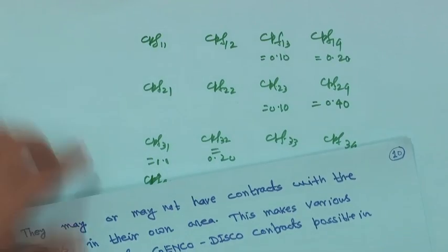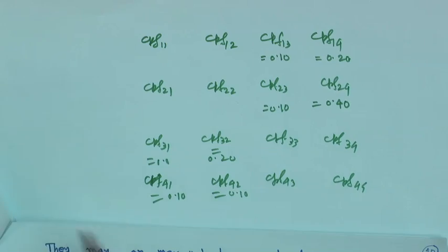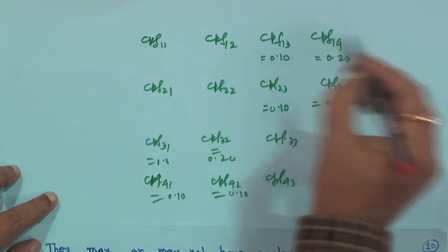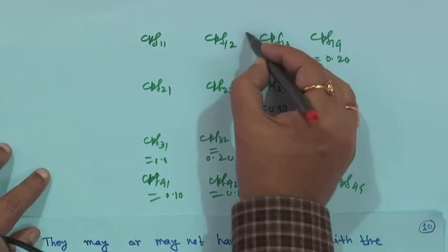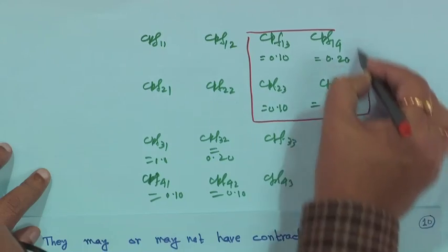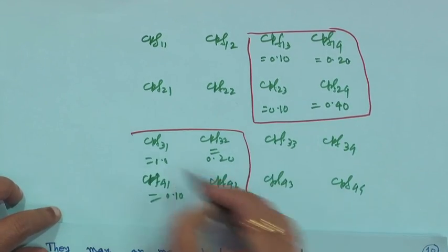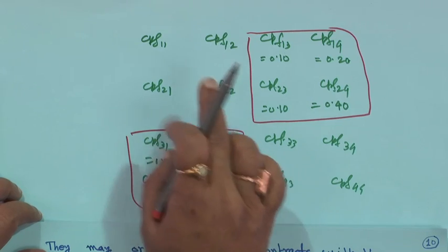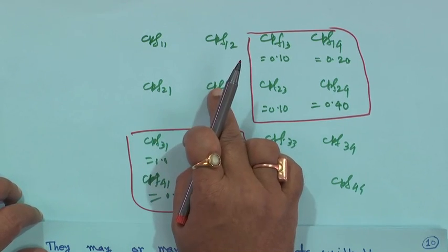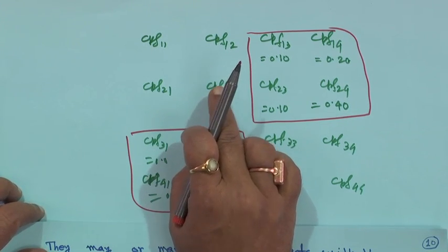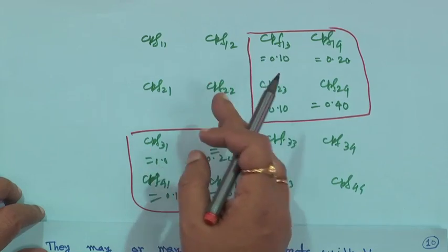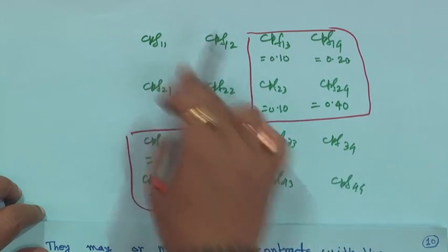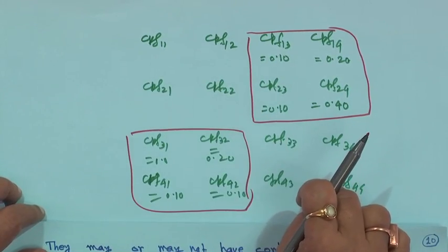That means in the tie-line power schedule equation, in the 1-2 direction only this portion comes, and here only these portions come. This is related to the DISCO's power demand. If any such element is there, it means the DISCO is demanding power from the GENCOs of its own area, so these will never come into the tie-line power equation, right.